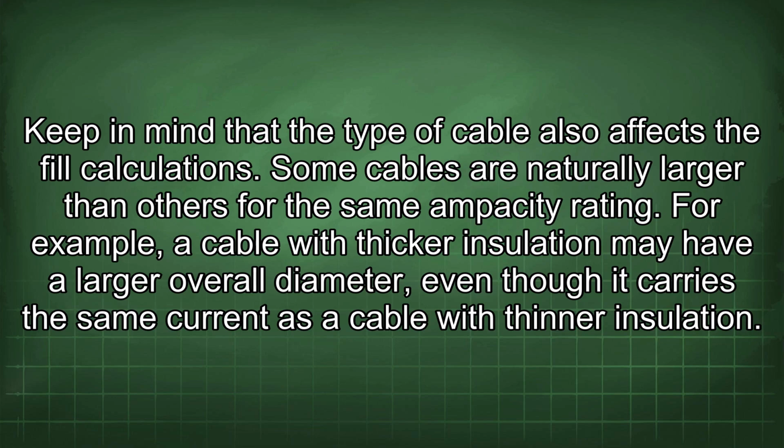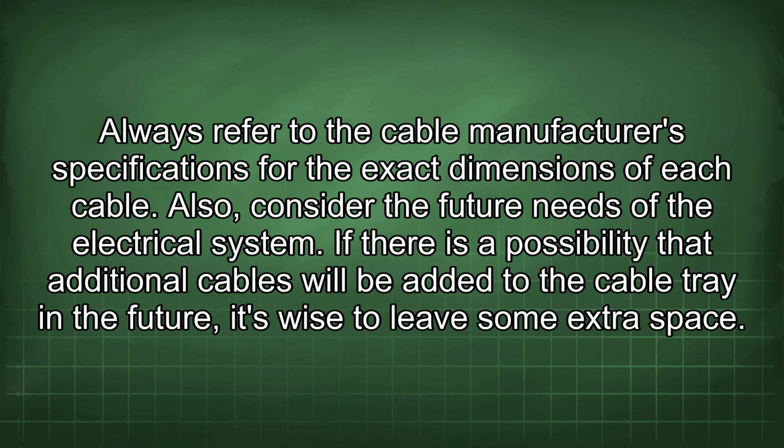Keep in mind that the type of cable also affects the fill calculations. Some cables are naturally larger than others for the same ampacity rating. For example, a cable with thicker insulation may have a larger overall diameter, even though it carries the same current as a cable with thinner insulation. Always refer to the cable manufacturer's specifications for the exact dimensions of each cable.